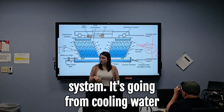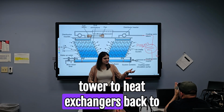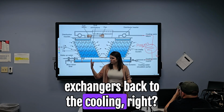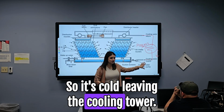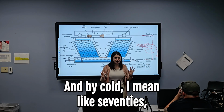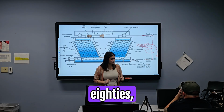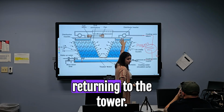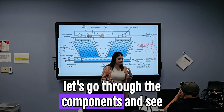It's going from cooling water tower to heat exchangers, back to the cooling water tower, to heat exchangers, back to the cooling tower. So it's cold leaving the cooling tower, and by cold, I mean like 70s, 80s. Cold leaving the tower, absorbs heat, warm, returning to the tower. Let's go through the components and see how they work.